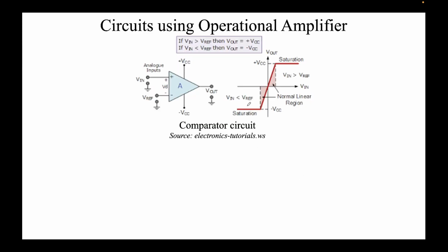And so this, I told you, an operational amplifier is used to perform some operations, and one of the very basic mathematical operations is comparison, like if x is greater than y or not. How do you do that? So you do that using this circuit diagram. You see this is some V reference to the negative terminal, we are providing some reference, right? And this is the input that I'm providing to the positive terminal, right? So if V in is greater than V reference, right, the output voltage is saturation, is plus VSAT.